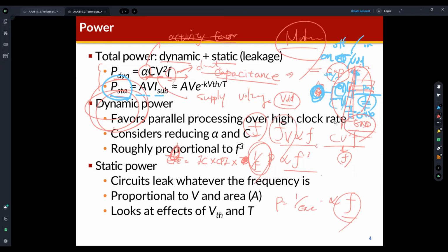This path is disconnected, because when the PMOS is off, the NMOS is on, and when the PMOS is on, the NMOS is off. So this path is usually disconnected, and connected only for a very short time. That's why the CMOS transistor is better than the traditional BJT.